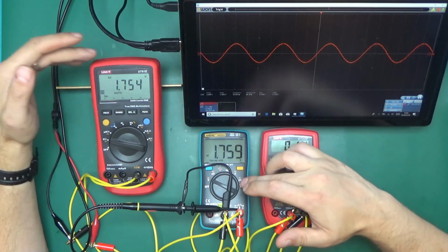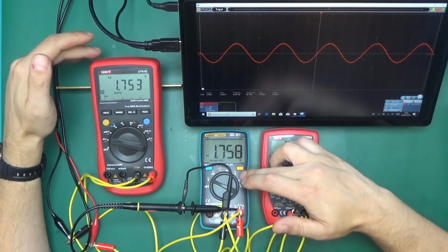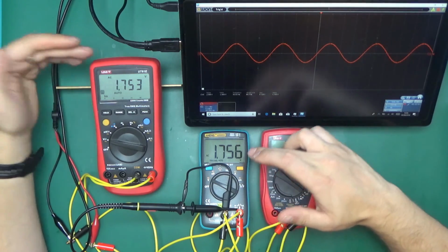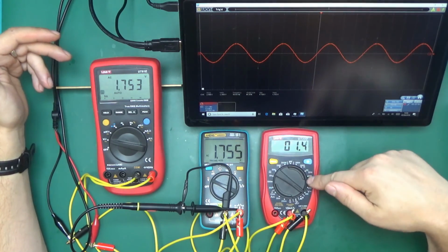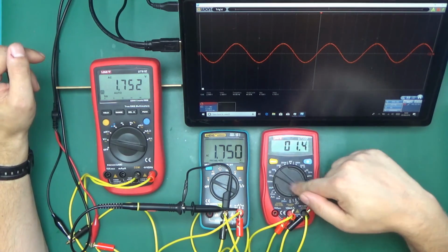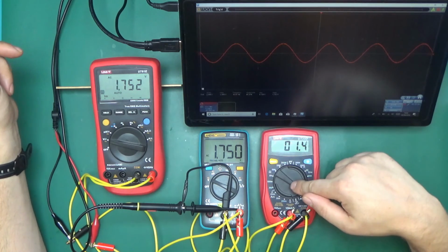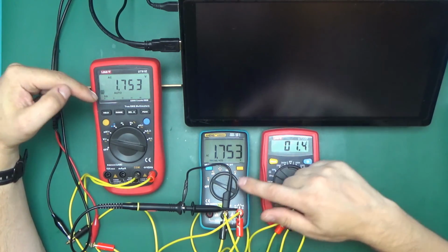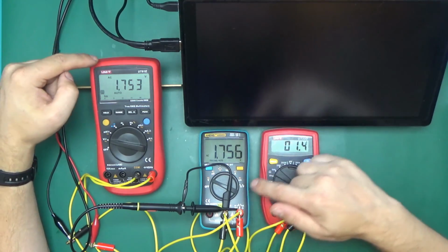Perhaps the true RMS multimeters are designed only to measure a sine wave, different amplitudes and frequencies, and the reading is a little bit more accurate. As you can see, this one's showing 1.4. Again, that's 50 Hz, so that's perfectly within the bandwidth of what this should measure. Even if this was using some lookup tables, it should be able to show a little bit more accurate. 1.75 is right what it would be for this waveform.